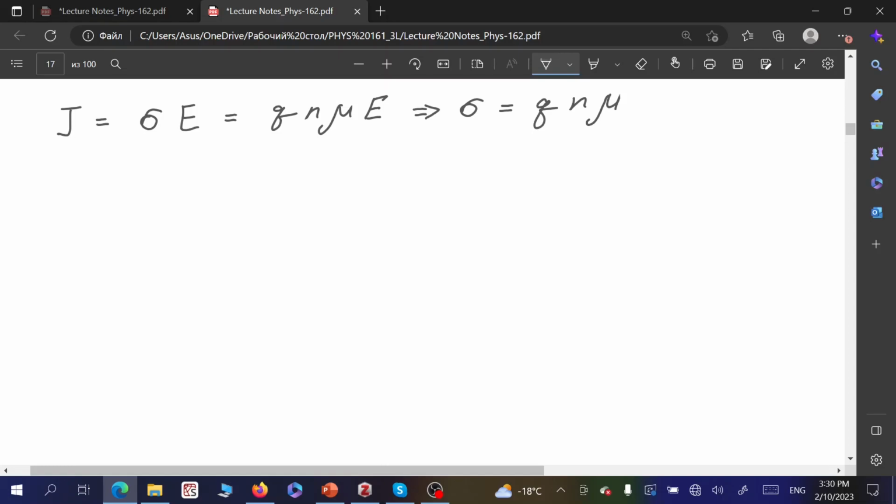So we just considered an example of how we can measure electric current. We use this torque exerted on a closed loop in an external uniform magnetic field. We can calibrate this device according to the angle by which the closed loop will rotate when we reach balance between the torque from the magnetic field and the torque from the string.